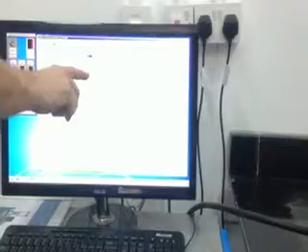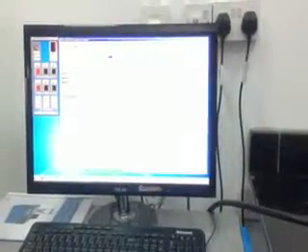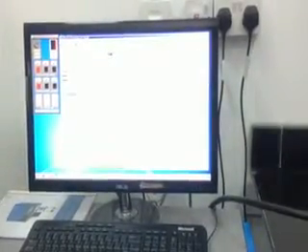This is the error, and this is the load drift. I think the load drift is for if you're not maintaining your right level, let's say your load's dropping off. So standard error should not go over 10%. With this IPC machine, we can get very good load error. I think initially they had the specification for 5% and under, but some of the other equipment manufacturers weren't able to comply under 5%, so they relaxed it a little to 10%.